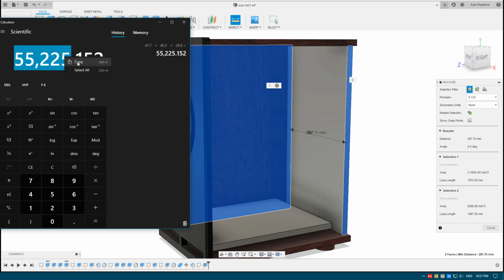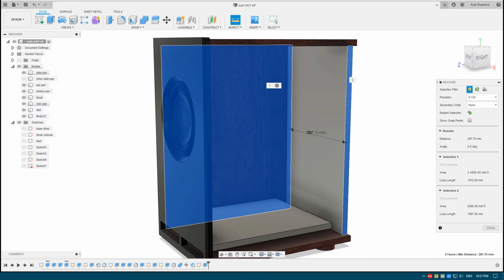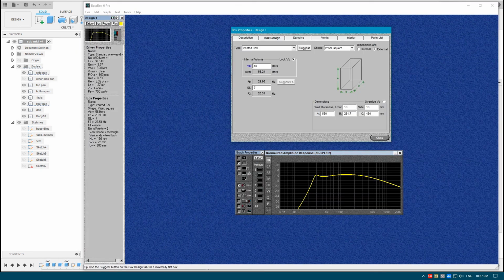That gives us a big number, in cubic centimeters, because I was doing this all in centimeters. If you do it all in millimeters, that will be a much bigger number, in cubic millimeters. So just punch that number into Google, cubic centimeters to liters, and that gives me 55 liters, which is a tiny bit out, because I want 56 liters, but that doesn't matter.